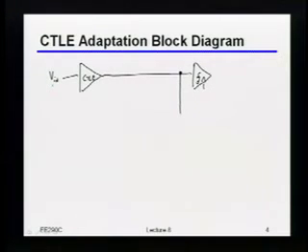It's basically an FFT engine, but just a 2-point FFT. Oh, okay. You could actually do an FFT. By the way, remember I want simple and low power. So I think I need the ADC and the FFT. I guess you're right, a 2-point FFT is not so bad, but I think I can do it with less overhead than that. But that is indeed correct. There's another minor caveat, which is my signals aren't guaranteed to be periodic, but we'll ignore that too.